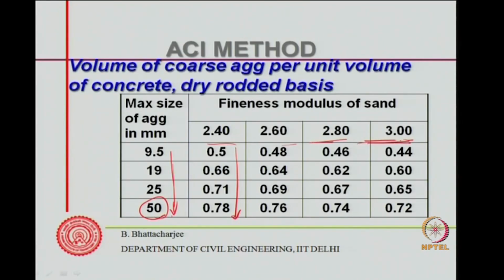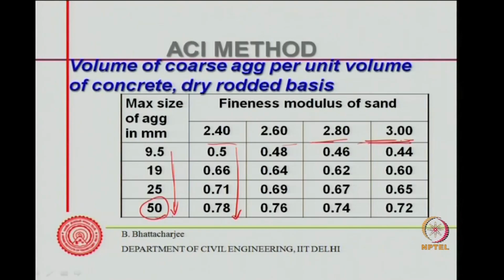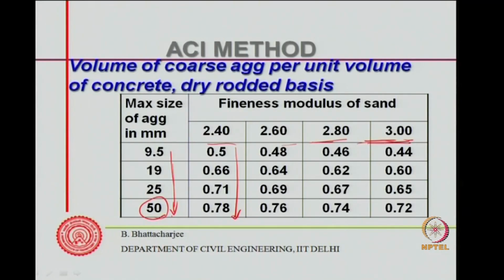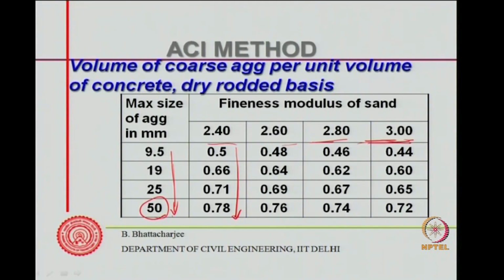Higher fineness modulus means coarser sand, which means better grading of the sand itself. The sand packs better, and more larger sizes are also available in it.